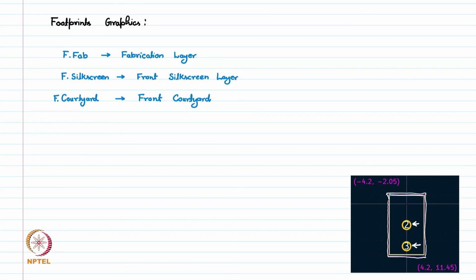It means no other component, for example some transistor here, some capacitor here, should go closer than this boundary. This boundary is reserved only for the switch. Any component should not be placed overlapping this boundary. So this is something called courtyard.